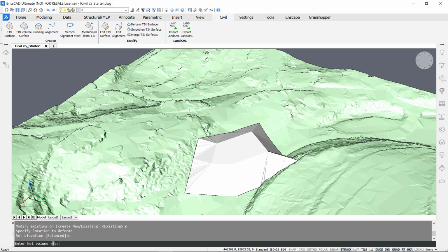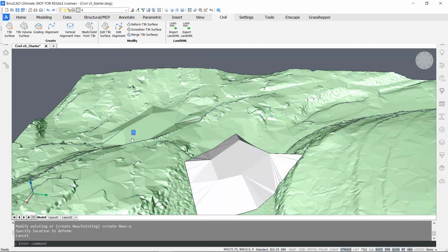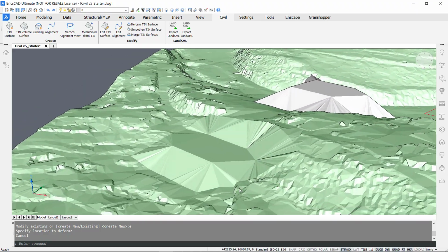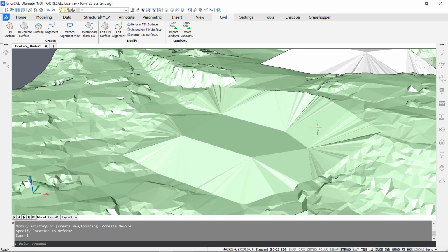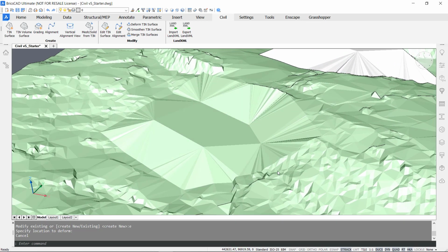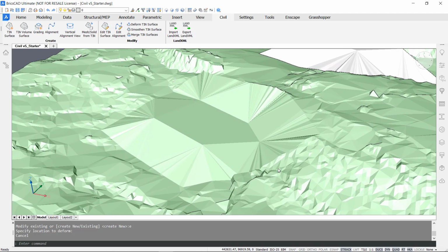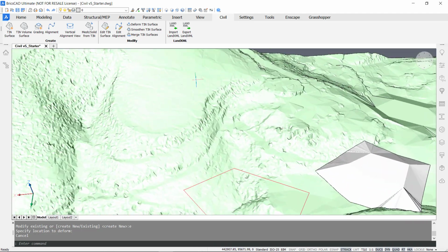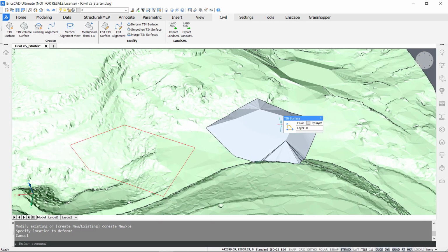So that's when you cut out volumes in the earthworks, you fill up with the same volume, so you don't need extra material, for example, which is cost efficient. Like this, you can specify the 0 net volume, and it will calculate the elevation for you like this. So this is the result when you use all your cut volume into filling this elevation.